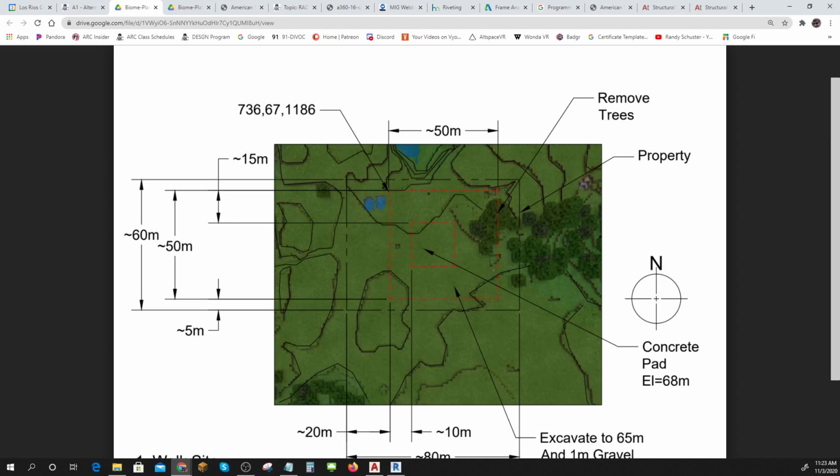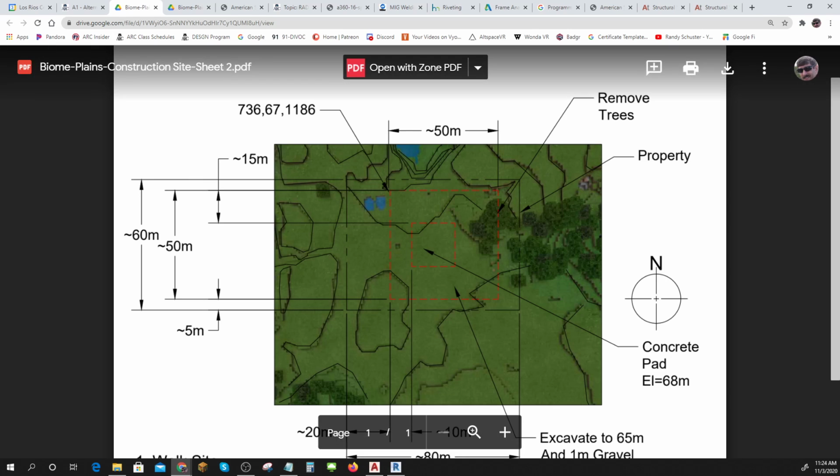We will be using this site in Design 350 as a sanitary drain development project for trying to locate a septic tank. You cannot be more than 150 feet from clear water, running surface water or even underground water, with septic. So we have to figure out if there is a place that we can put septic on this site. You don't have to do that, but we'll be doing that.